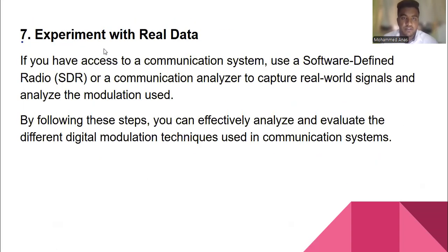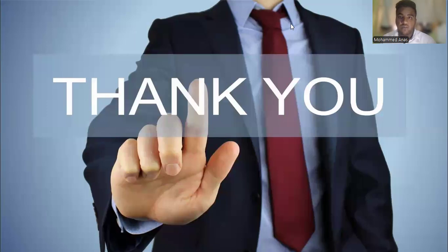Experiment with real-time data. If you have access to a communication system, use a software-defined radio (SDR) or a communication analyzer to capture real-world signals and analyze the modulation used. By following these steps, we can effectively analyze and evaluate the digital signal modulation techniques used in communication. By using all these steps, we can analyze the different digital modulation techniques used in communication systems.